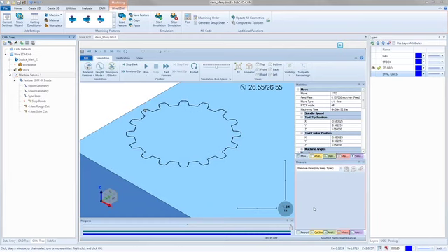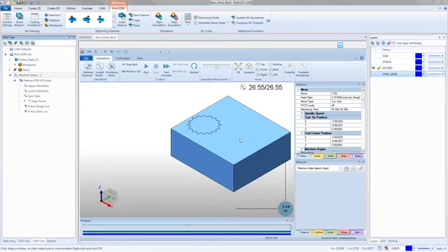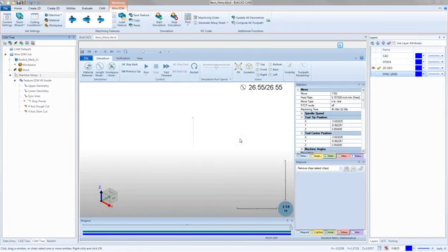What's weird, and it's in a weird spot, I get it, but with the measure tab, you can actually go in and remove chips. So you have remove chips, only keep one part. You have remove chips, select chips. So I'm going to use remove chips, select chips. And I'm going to click on the main part of this solid here, this big old block here, because I want to get rid of that. Oh, we didn't break all the way through somewhere. So normally it would go in and get rid of just the part that I want to keep.